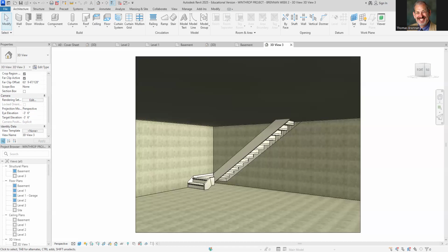Okay, looks like you guys will have the stairs here. So now the next thing is to get the stairs in place. Let me show you. Save your work, and I'm going to take over your screens again, because to get these to go from one level to another, there's a little trick. It's going to make it real easy for you, because getting the stairs can be the biggest royal pain, or it can be really a dream.